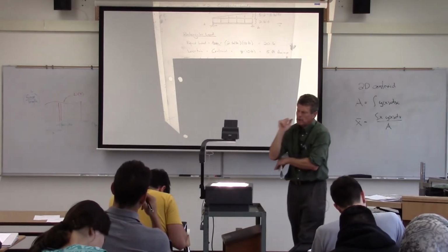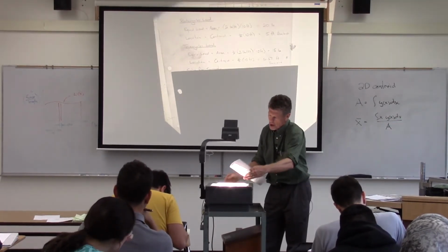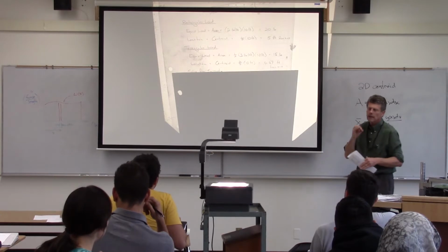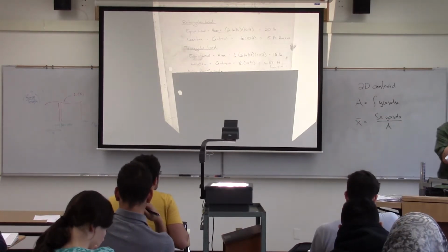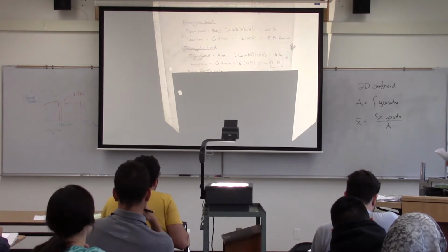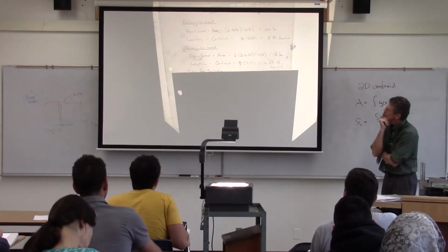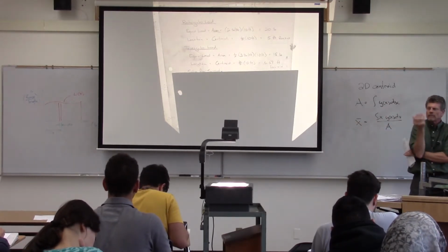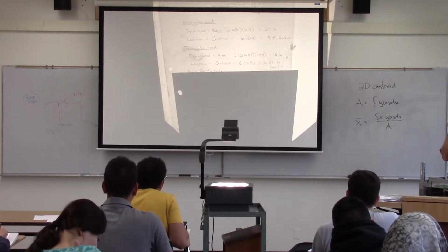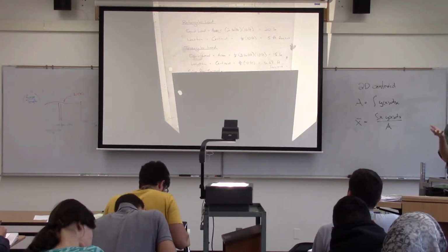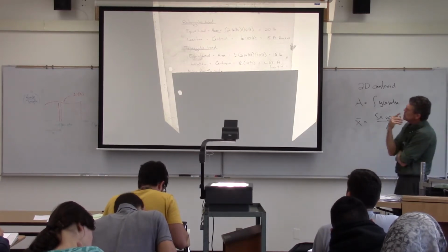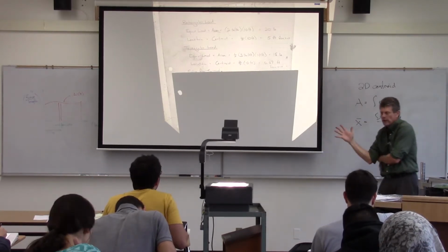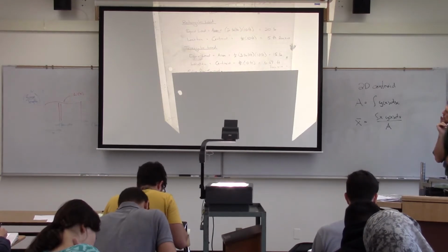And then the next one's the triangle, and again, commit this to memory. It's always going to be 1/3 up from the base or 2/3 from the pointy end. That's one of those ones I'll expect you to know: triangles, rectangles, circles. The area is just going to be half that of a rectangle, so base times height times 1/2. Basically, we'll find that the triangular area is 15 pounds. And then its location from that A point is going to be 2/3 over, again 2/3 from the pointy end, or 1/3 up from the base, of 6.67.